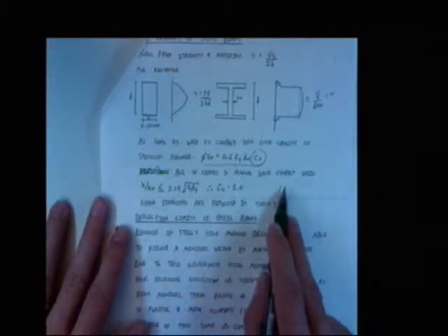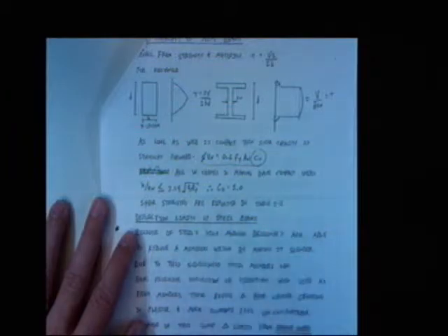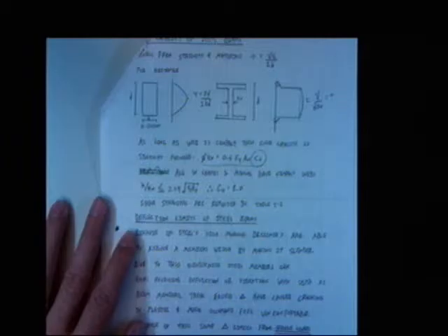What does that mean? I ask you that question. Compact. We've mentioned that word before. We're in zone 1 in the web slenderness snail chart. Remember, we have 3 snail charts. One for lateral torsional buckling, one for slender flanges. Is that a problem for rolled sections? Only for about 6 sections, right? The actual reduction in capacity is like about 5% or so, right? So I'd say no, it's not a big deal for rolled sections.